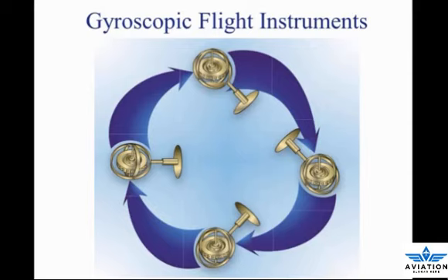There are two general types of mountings. The type used depends on which property of the gyro is utilized. A freely or universally mounted gyroscope is free to rotate in any direction about its center of gravity. Such a wheel is said to have 3 planes of freedom. Restricted or semi-rigidly mounted gyroscopes are those mounted so that one of the planes of freedom is held fixed in relation to the base. There are 2 fundamental properties of gyroscopic action.